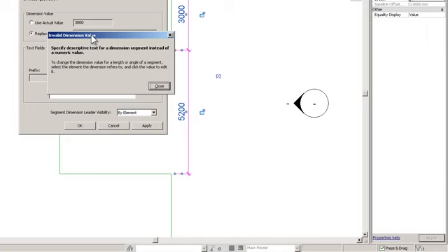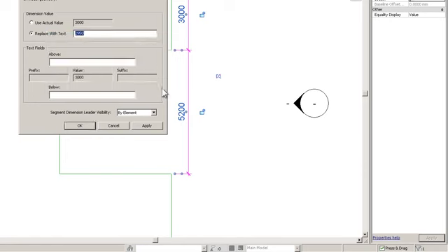I've had people working on projects that I've been running who have done that, simply changed the dimension in AutoCAD to try and suit what they thought it would be. The building got built, it was a bathroom, and the bath didn't fit in the bathroom. You should never ever override a dimension. I know most of you don't need telling this, but there are some people out there who will do it. Revit, fortunately, doesn't give you the option. It does not allow you to update it with another numerical input.